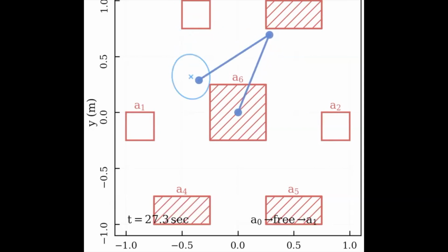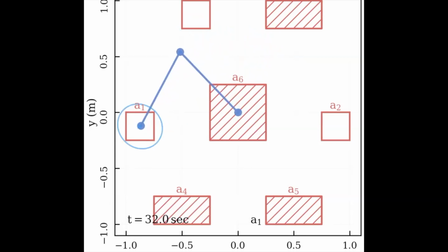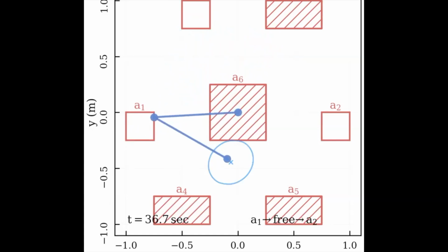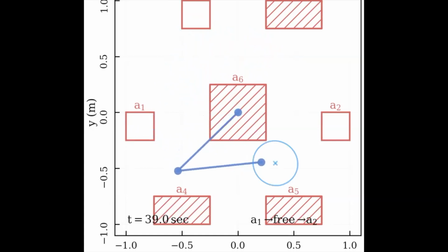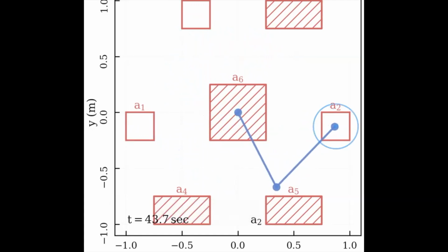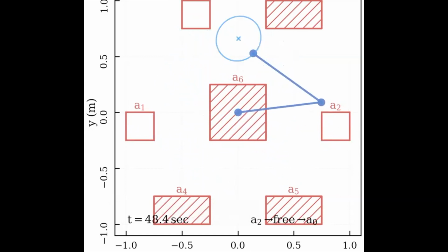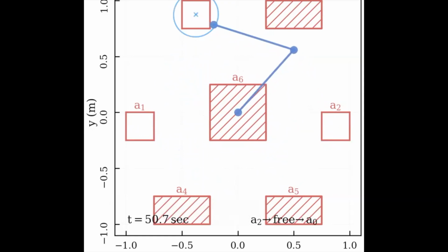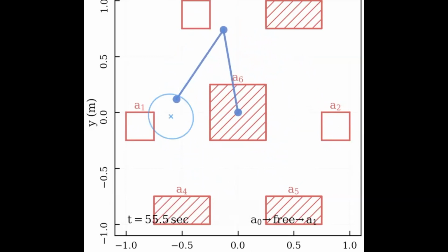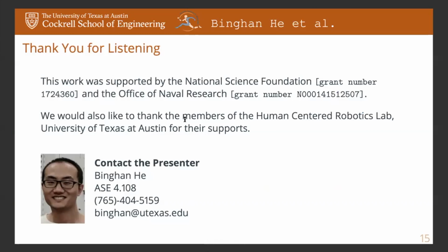Every time, this end effector starts from the edge of this ellipsoidal shape and goes to the center, but before it really reaches the center, it enters another barrier pair. And the sequence of this barrier pair RRT will guide the robot end effector to move from A0 region to A1 region and to A2 region and back to A0 region again and again without going through any of these shadowed obstacle regions. That is all for my presentation.